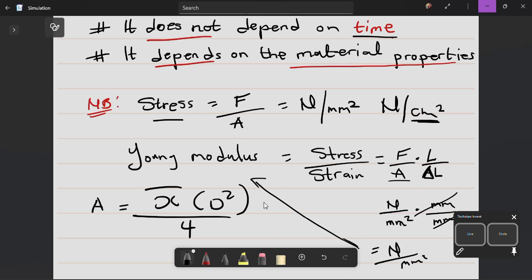But here, our focus is to use the FEA, which is the finite element analysis, to do the testing. You understand? So why are we using that? If you compare to the olden days, when a scientist or an engineer wanted to do a test like this, they had to go to a lab where they have devices. You have to get your material, let me say cast iron, for instance. You subject it, you put it under a load of 35,000 Newton. You apply the force of 35,000 Newton to it to see whether the material can withstand what you want to use it for. You understand? So that is typically what they did in the olden days.